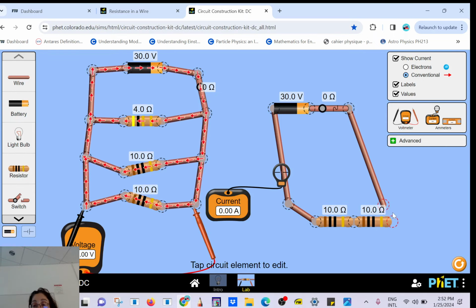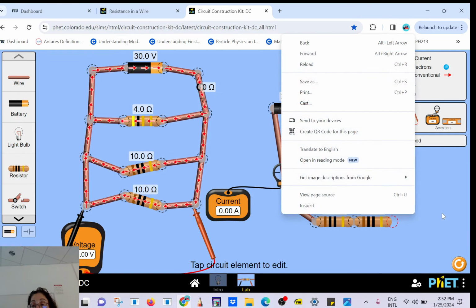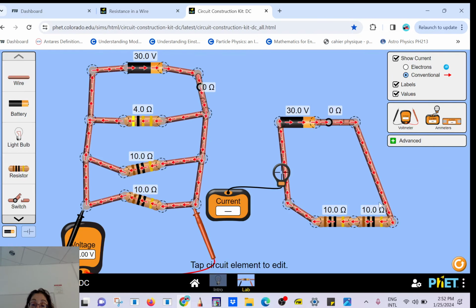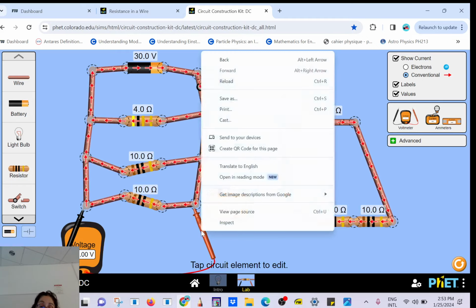Now you see that the current has been divided by 2. Instead of having 3, I have 1.5. So it's not happy because alone it's supposed to have 3 amps. And now it gets only 1.5 because when you multiply the number of loads by 2, and if the loads are the same, you divide the current by 2. In addition to that, the voltage is also divided by 2.